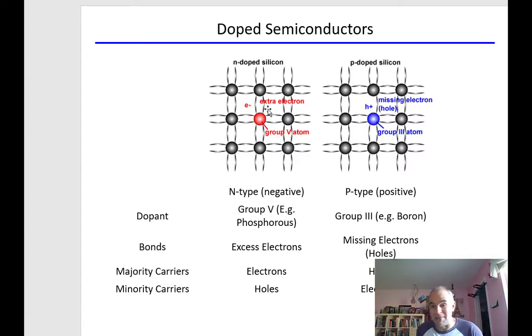And then at the same time, that causes the corresponding side to have a net charge. Again, this is neutral here, and that's neutral. But once these electrons over here move to here, and the holes over here move to there, then this becomes net positive, that becomes net negative. And so then you have a desire for the electrons to come back. And it's the balance between those two forces that maintains an equilibrium. Until you put the solar cell in sunshine.